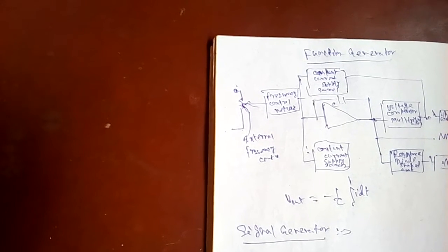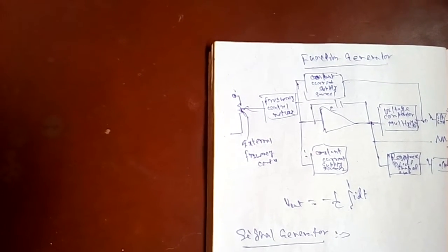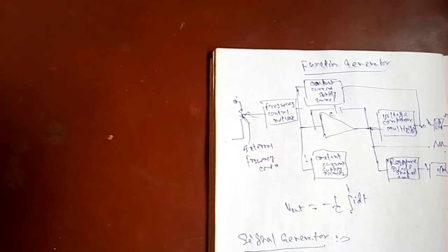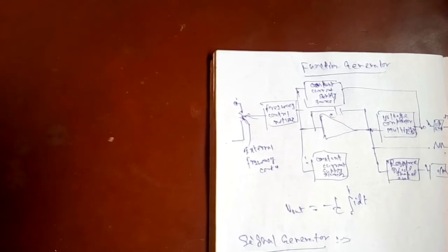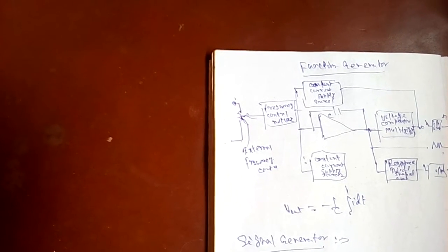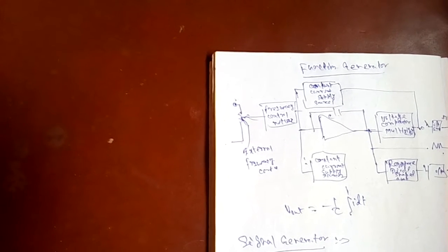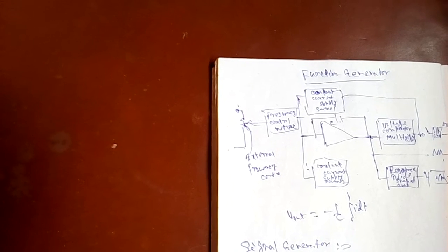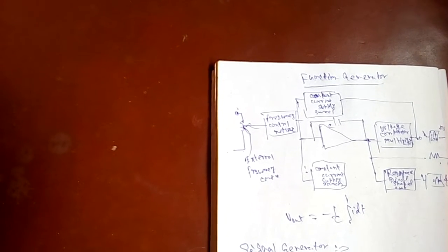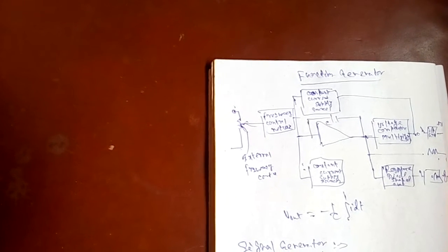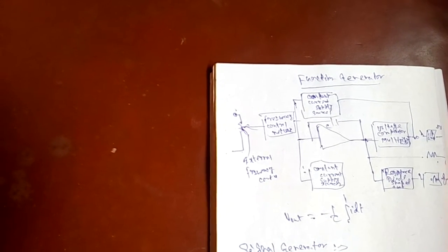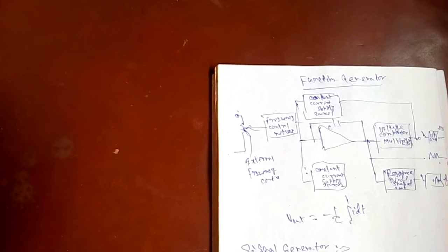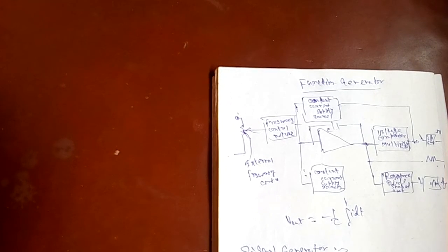The main difference is that when signal generators are employed for producing an unmodulated sinusoidal waveform, they are set to produce a continuous wave, high frequency signal. When the output signal is modulated, the modulating waveform may be either an externally applied sine wave, square wave, triangular pulse or complex wave, as well as an internally generated sine wave. Signal generators are primarily employed for providing appropriate signals for calibration, testing and troubleshooting of amplifier circuits in communication electronics such as radio and TV amplifiers.